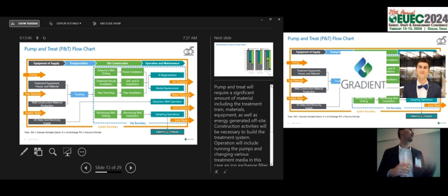The site construction is a little more complicated for this alternative. There's trenching, treatment house installation, and extraction wells to be drilled. And then the operation and maintenance was limited to extraction well maintenance, ion exchange regeneration, and media replacement changeouts.